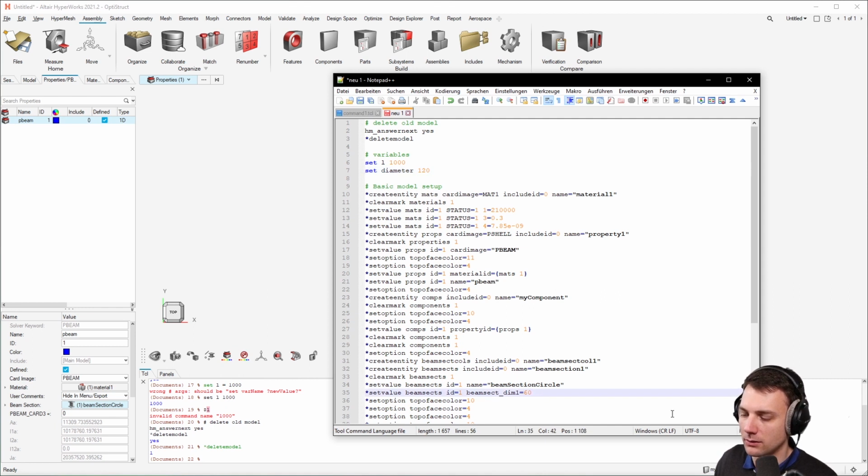And here comes the trick. If you want to do something like an equation here, you have to use the brackets. I think you have to type equation, or EQ. No. Eval? I think eval, for evaluate, because the way the interpreter interprets the language is which part of the line is executed first, and if you want an equation in there, you want the value of this equation to be computed before the rest of the line. So eval shows you that the content in the bracket is evaluated before the rest of the line. So this is it, and now let's see, it's diameter divided by 2.